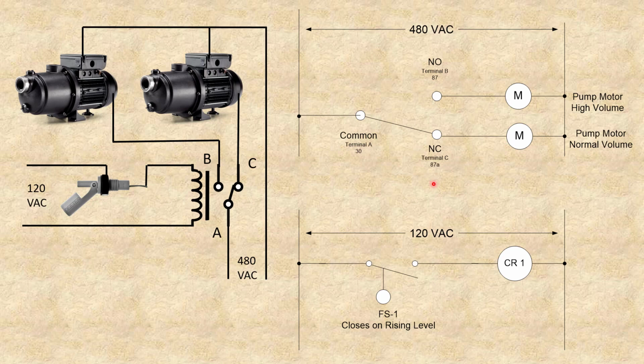So in this particular case, it's similar to what I had before, but in this particular example, I've got two different motors. And the one thing I wanted to point out here was I have two different circuits. I have a 120 volt control circuit that's here. That's part of it, so the coil is energized, operates out of 120, but my contacts, my power circuit, is operated off 480 volts. So effectively, I can control 480 volt circuits with a 120 volt control circuit.